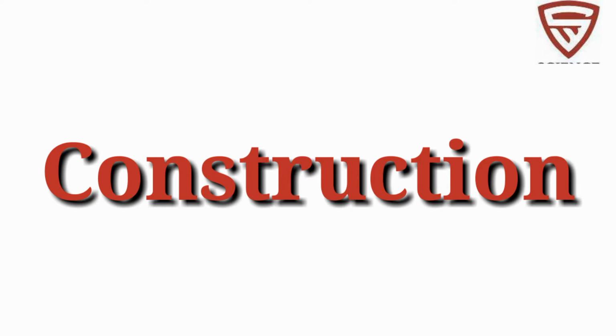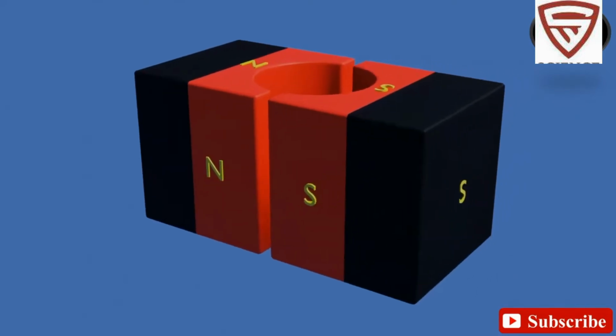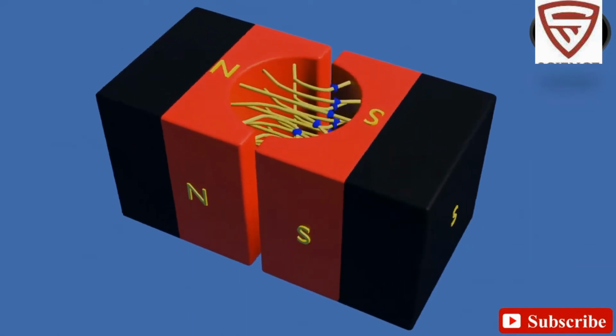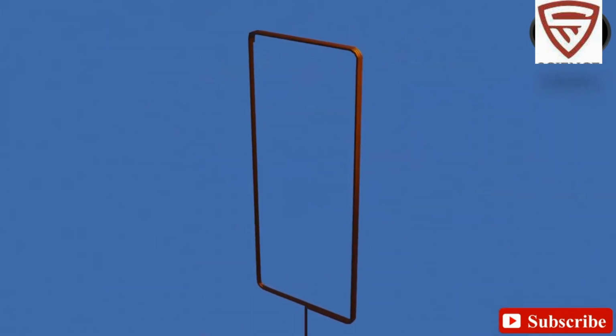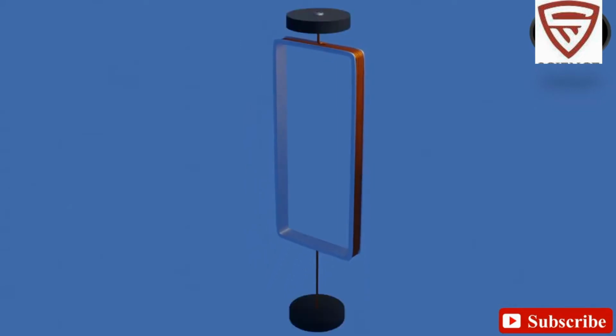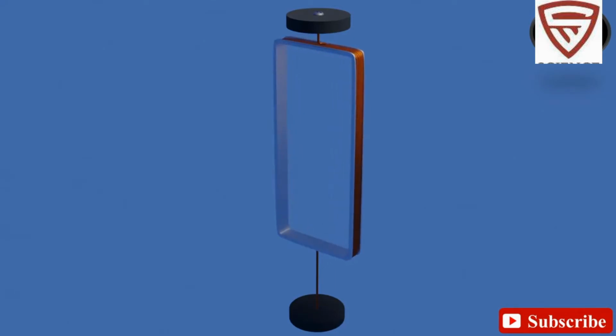First we will discuss the construction of the pivoted coil galvanometer. It consists of two concave permanent magnets where the magnetic field is directed from the north direction to the south direction, and a rectangular coil with a number of turns made of fully insulated copper wire is wound on a metallic frame. This metallic frame is pivoted at both ends, where it is free to rotate between the pivots.